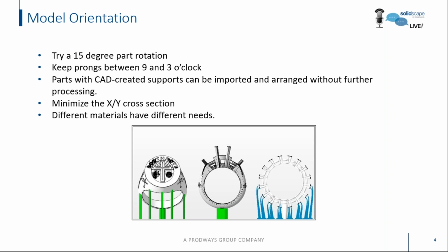Parts with CAD created supports can be imported and arranged without further processing if you have that software. Parts should be arranged to minimize the X and Y cross-section on any given layer. And just remember that different materials, different resins will have different needs.